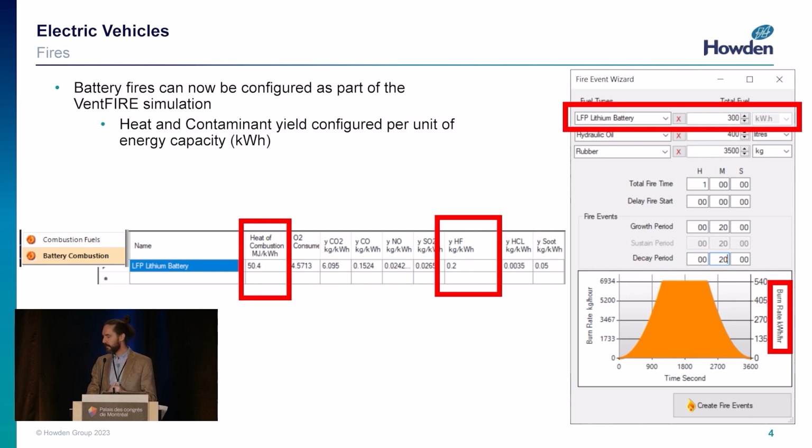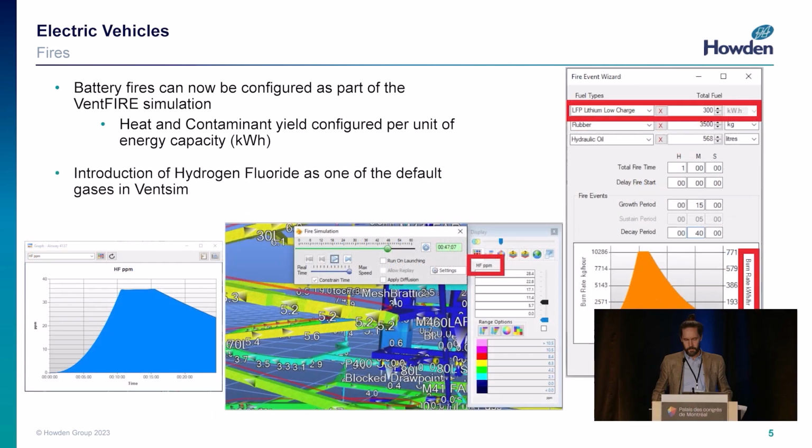So we started off with a value of 50% for this. What that's meaning is that half of the heat coming off your electric vehicle is going to come out as latent heat. And you might adjust that setting depending on the type of mine you're in, how wet it is. But as I said, nothing's set in stone there, and that's something that we're keeping an eye on.